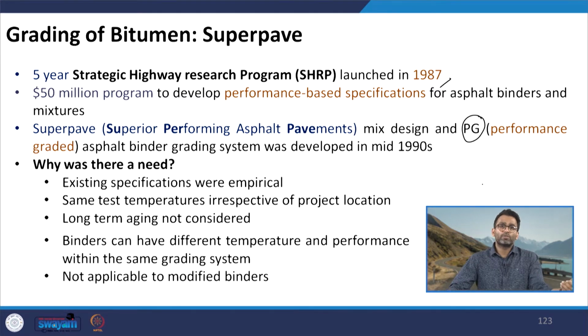It was also observed that in the viscosity grading system, which was the earlier specification, binders can have different temperature susceptibility and different performance characteristics, even though they fall under the same grading with respect to the viscosity grading system. This I will show you in the next slide through a graph.